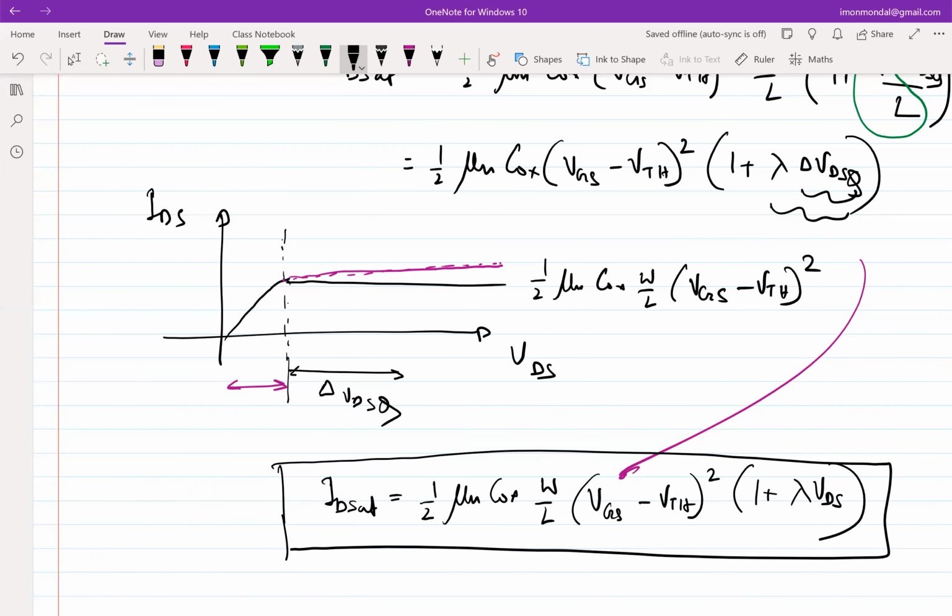I mean, what are the effects? What are essentially the knobs that you need to have to influence the characteristics of a transistor, right? So don't get too much bogged down with the fact that this is square, that is linear, and so on. So what you need to understand to be a good designer is, what do I need to do to increase the current? What do I need to do to decrease the current? How much it will increase by or how much it will decrease by is best left to the numerical simulator, right? Or a calculator, right? But as a designer, you need to know what should I do to increase something or decrease something, right?